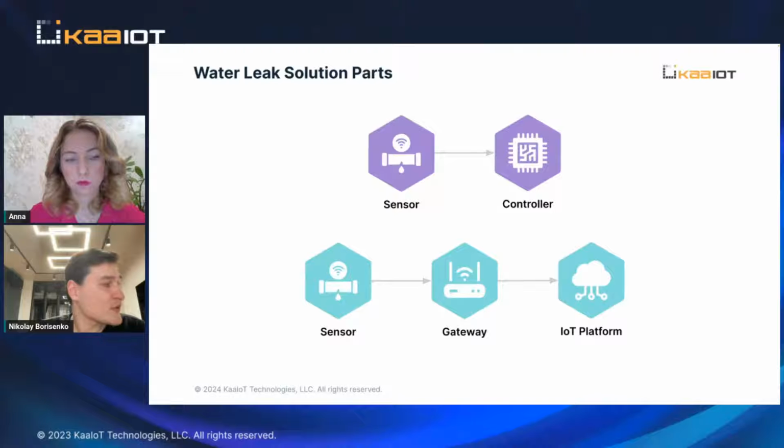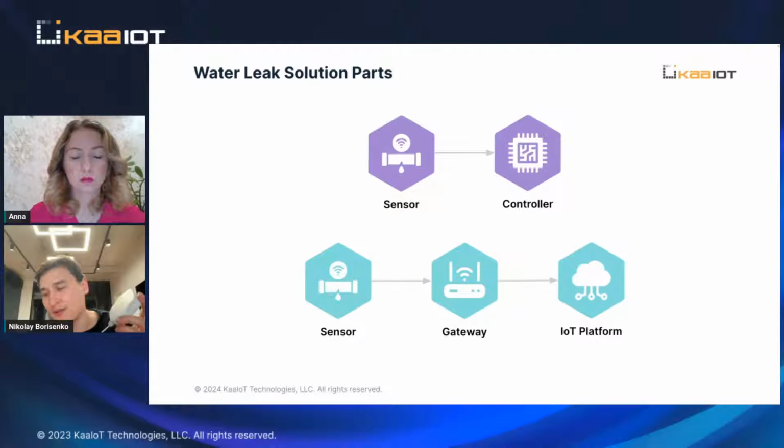Another thing which is important when you select sensors is how it works. Here I have only one dry contact, and it can cover, I don't know, 20 square centimeters of range, and it will detect a leak. Each of these contacts should become wet to get a trigger.